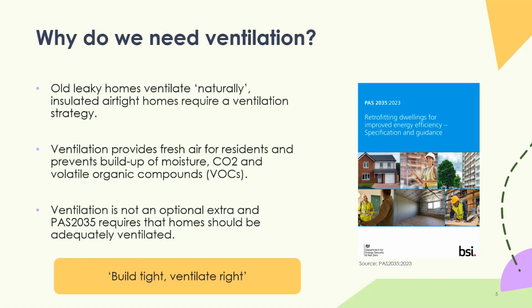And when you're ventilating a home, you're basically removing stale air, which has a buildup of moisture from washing, cooking, respiration, CO2 from respiration as well, and VOCs, volatile organic compounds, which are emitted from all sorts of different things, curtains, furnishings, carpets, paint. Lots of different materials that we have in our homes are emitting various levels of chemicals that are used in their finishes.